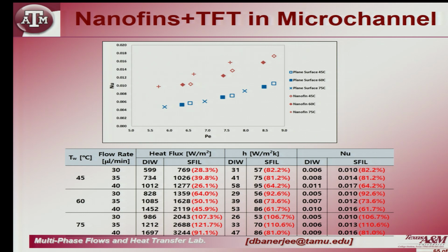This is pure water without any nano fins. This is pure water with fins, and you can see a jump which is of the order of 20 to 80%, and it mimics our nanofluids experiments. So, this definitively shows that these precipitated nanoparticles are the ones that are giving you the enhancement, okay, which actually has a very fundamental implication.